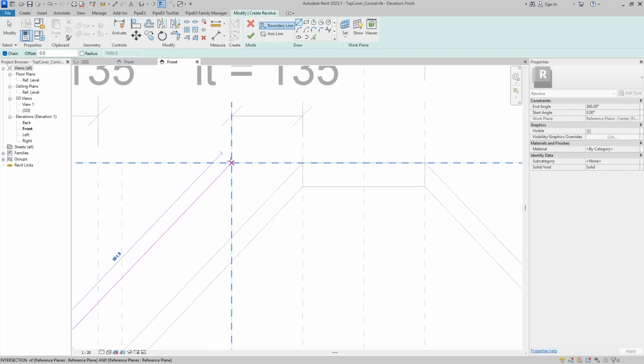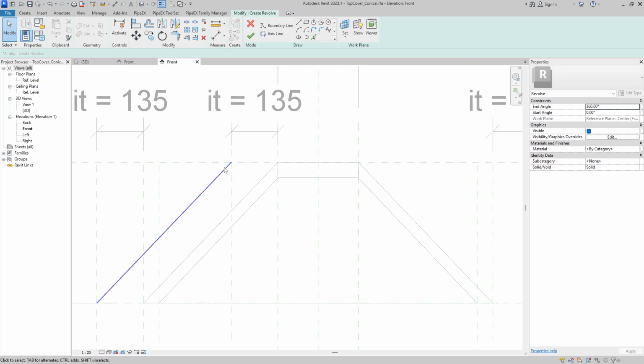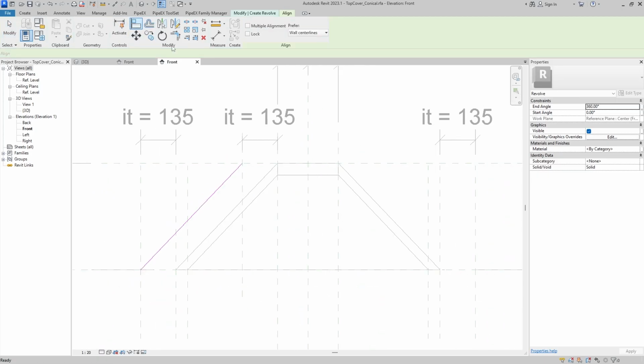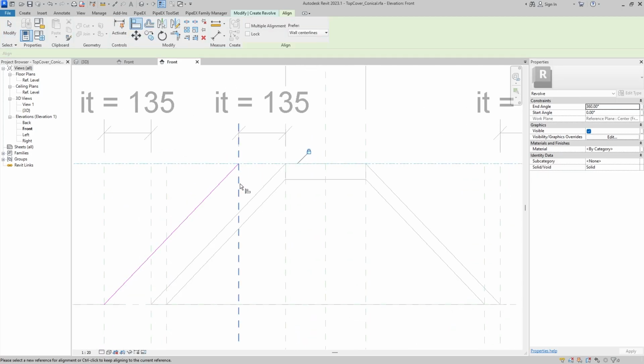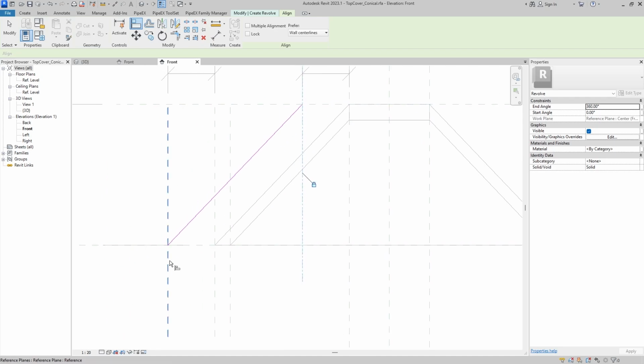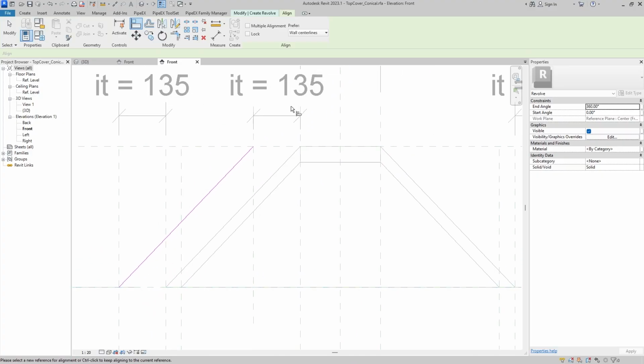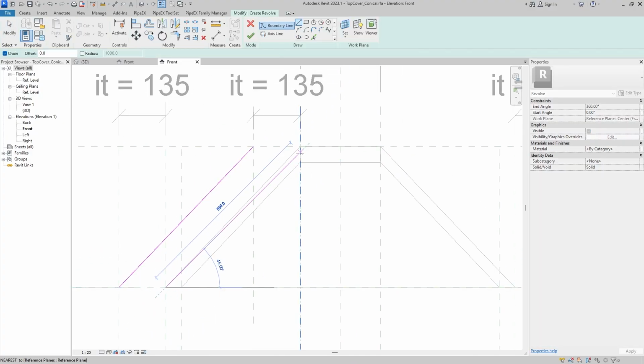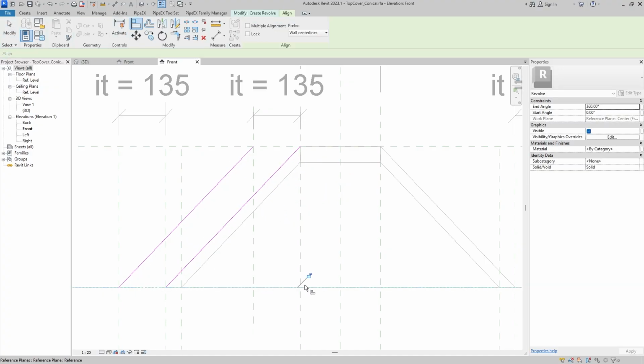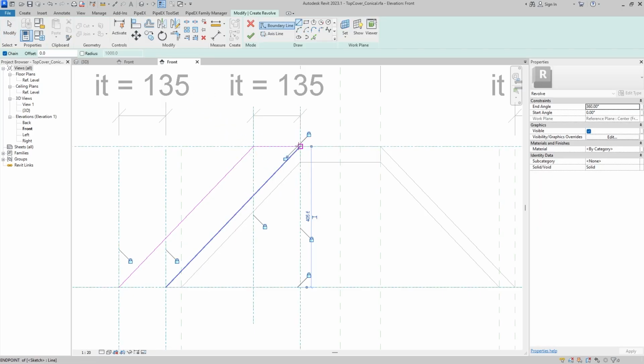And just to ensure that it will always be locked in place, we define the extra reference plane, and we're going to bind it to that newly defined reference plane. Then we will just use reference planes defined here just to lock the geometry. And close it.